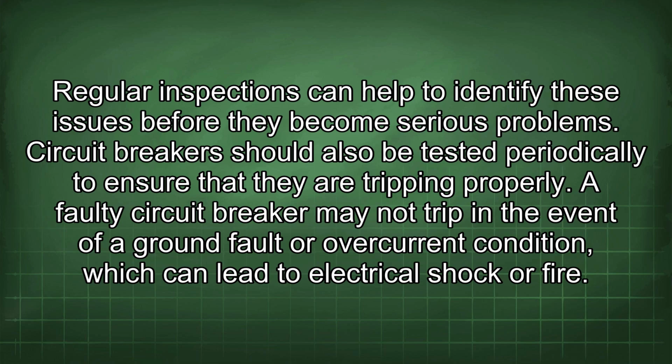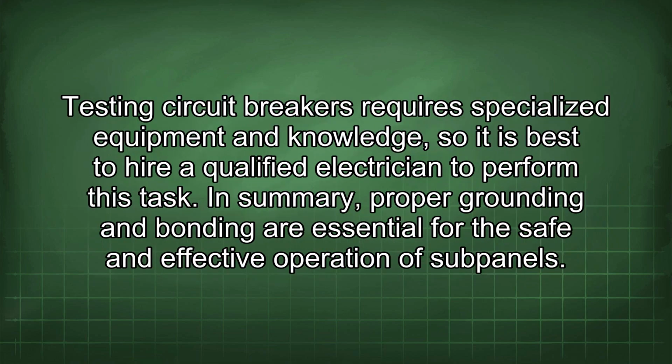Circuit breakers should also be tested periodically to ensure that they are tripping properly. A faulty circuit breaker may not trip in the event of a ground fault or overcurrent condition, which can lead to electrical shock or fire. Testing circuit breakers requires specialized equipment and knowledge, so it is best to hire a qualified electrician to perform this task. In summary, proper grounding and bonding are essential for the safe and effective operation of subpanels.